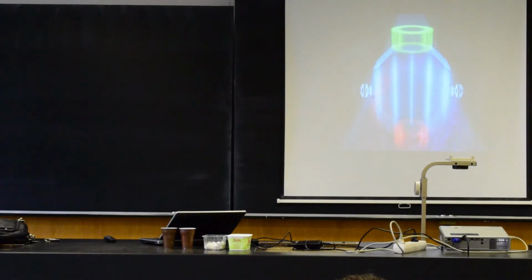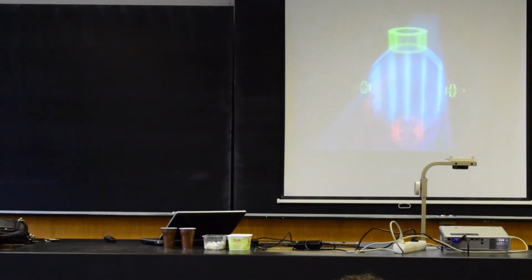As a result, the positively and negatively charged particles in the liquid are separated and collect on the opposite sides of the tube wall. Now an electrical voltage forms, which is detected and measured by the two electrodes. This voltage is directly proportional to the flow velocity in the pipeline. Together with the known